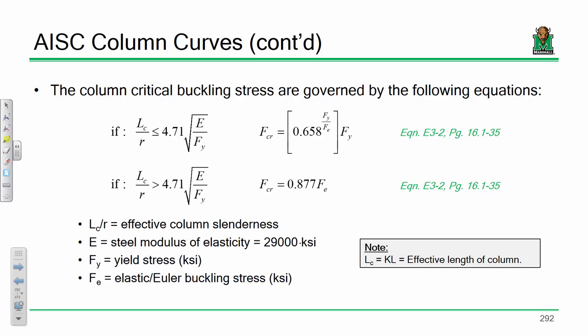So this is chapter E3 or section E3. So if you do not have to consider local buckling, you're using the equations that we've presented before. And let me be clear, 99 out of 100 times, you'll never have a situation where you don't use section E3. This is what you're going to be using just about every time, for the most part, even in practice. When I say that, I'm talking about column design and beam design in buildings. In bridges, that's a different story.